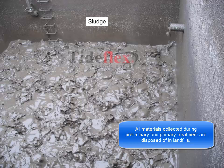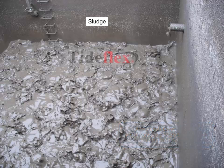The stuff at the bottom has settled out. The water's been drained out just to look at this picture, but while the water is in there, this stuff settles to the bottom. We call this sludge. All right, and again, we'll have this sucked out, or it'll be scraped out and then disposed of in a landfill. So the point is, the water in the middle, it's cleaner. It's still gross, but it's still clean. We've settled the particulates out. The greases and oils have floated to the top.